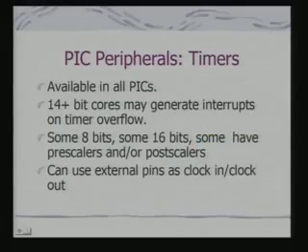Next we look at timers. Timers are very important peripherals for any microcontroller because timers are used for synchronization with other devices, taking care of various timing requirements for control applications. And there are a number of timers, in fact typically 3 timers on mid-range PIC microcontrollers. And what do we mean by the 14 plus bit codes? When your instruction length is 14 bits, these codes enable the timers to generate interrupts on overflow.